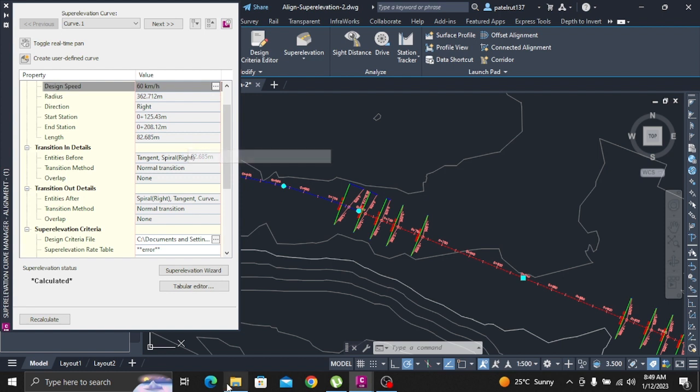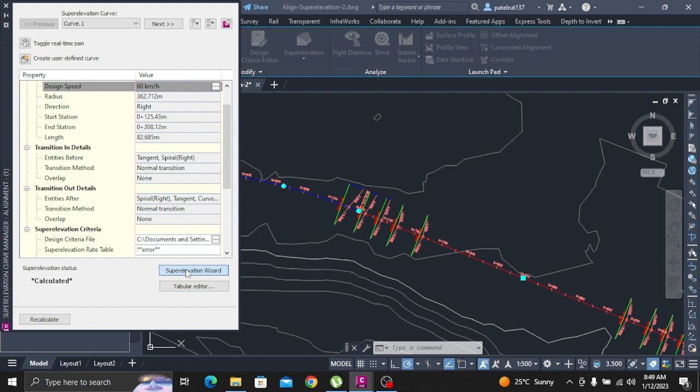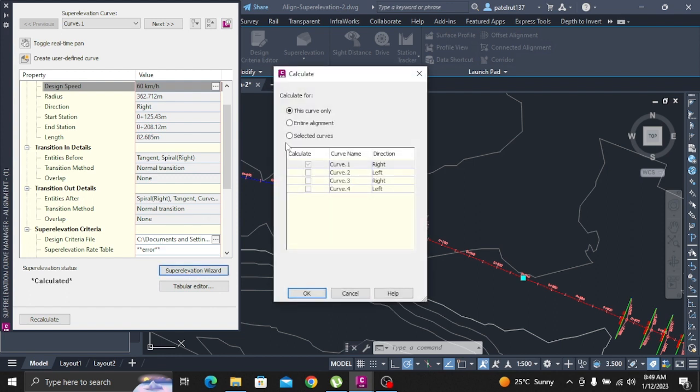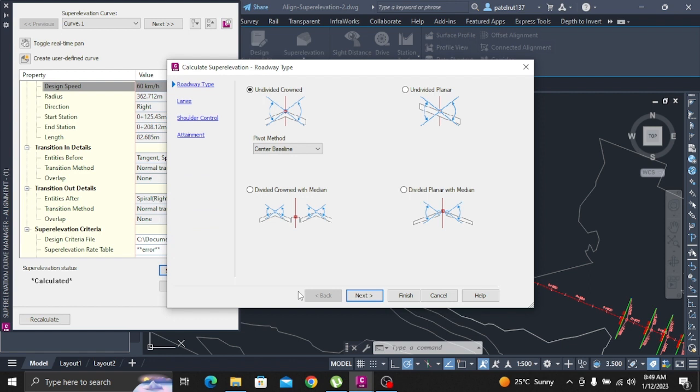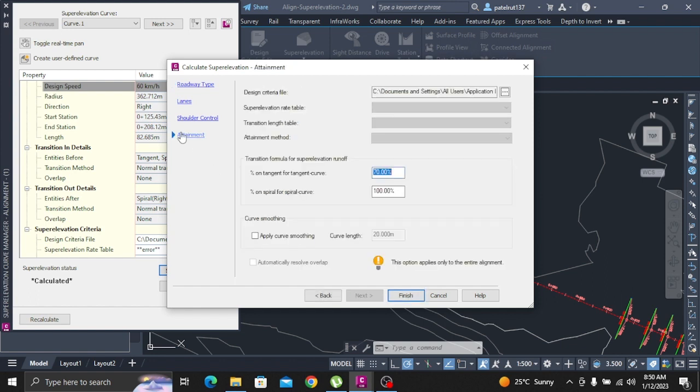Press Escape. Open Align Superelevation 3.dwg, which is located in the Tutorials Drawings folder. Select the alignment. Click Alignment tab, Modify Panel Superelevation drop-down, Create Superelevation View. In the Create Superelevation View dialog box, under Superelevation View Style, click Edit Current Selection.